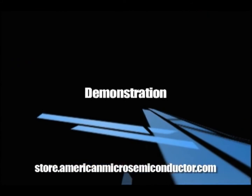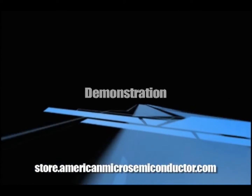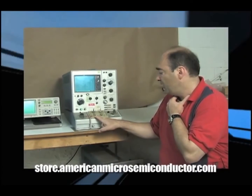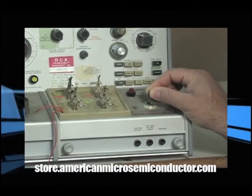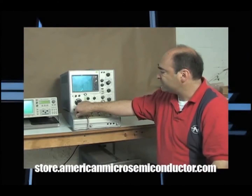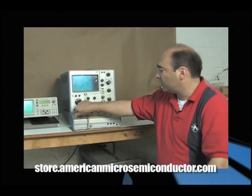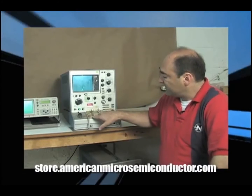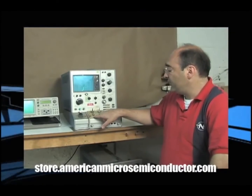If you look at the curve tracer and at the characteristics, here's what you're going to see. On the left-hand side, I have a standard 1N4001. I'll flip the switch so we can look at the forward voltage characteristics. Here you'll see conduction beginning to occur at about 0.5 of a volt. Now, let's switch over to the tunnel diode.